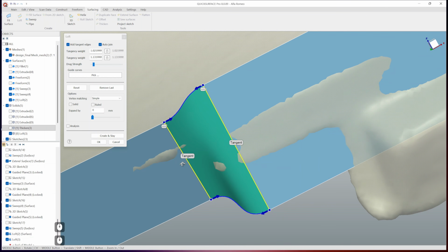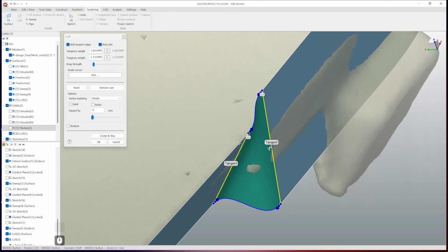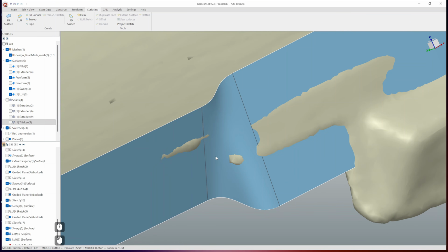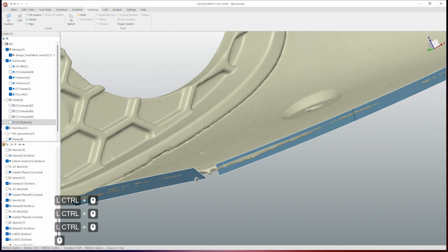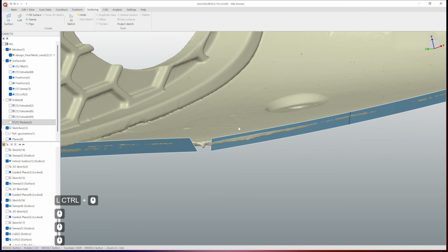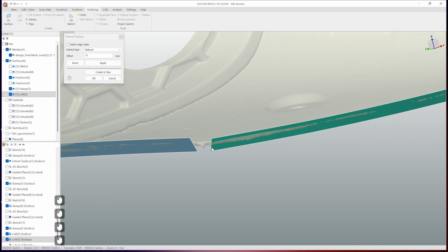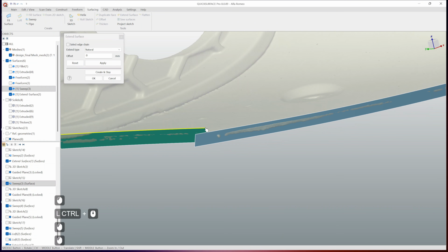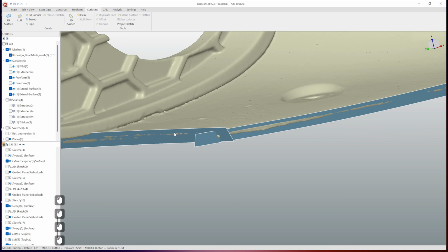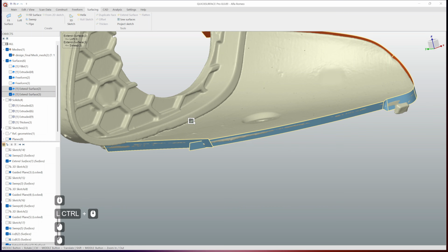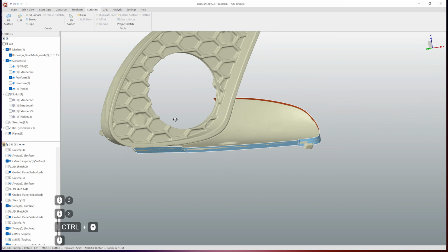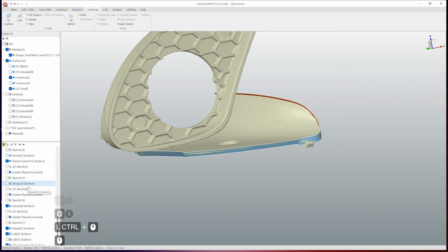Of course we can extend sweeps slightly here to make it sharper, but for general use this should be just fine. So what we are going to do on this side, I'll hide my sketch, and I want to extend the sweep slightly longer, and I want to extend this one as well to intersect them. Okay, like this, so I can trim them. Okay, this looks good.